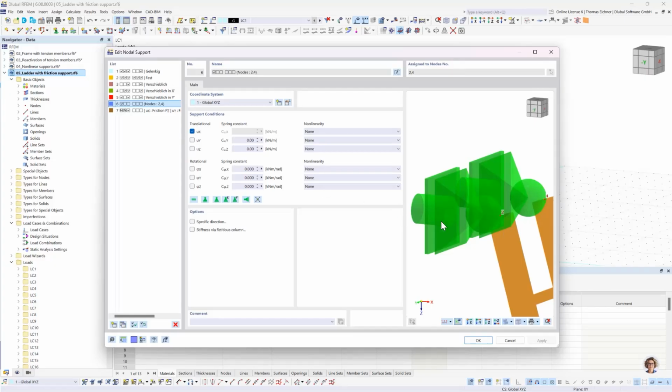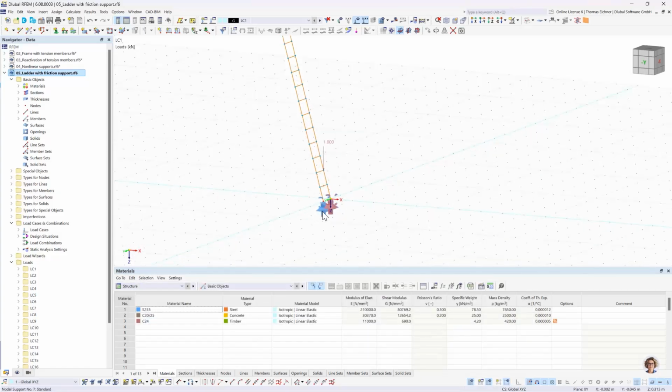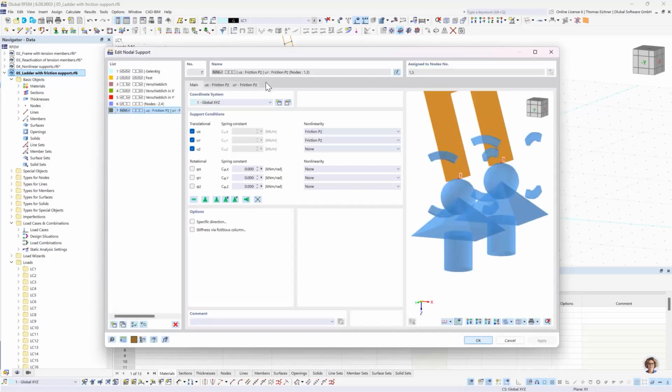So it leans to the building and it's only supported in x direction. On the bottom, it stands on the ground, so it is supported in z direction. We could also implement a failure if negative, but that's not needed right now since we only have vertical forces from the top to the bottom, so it's gonna hold anyway, so this is not needed.